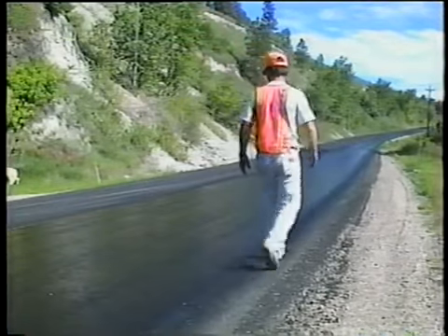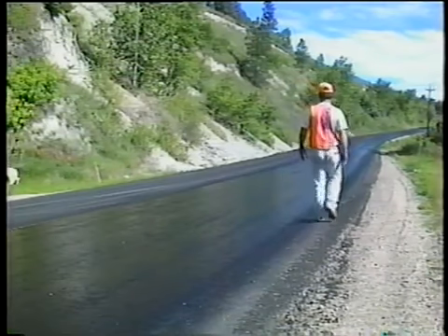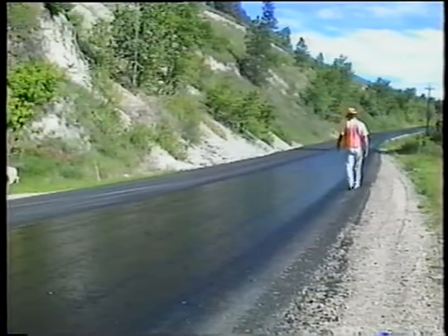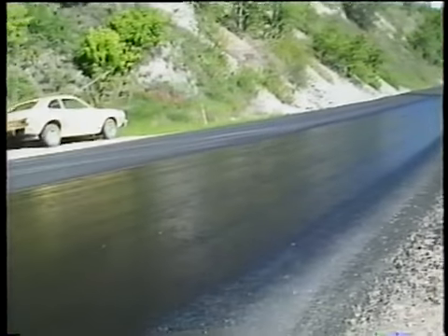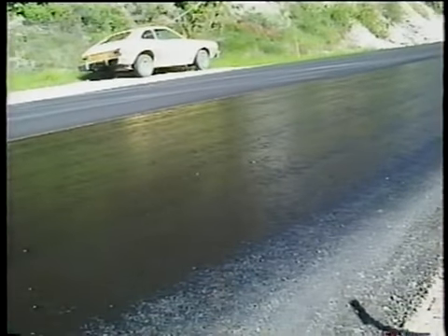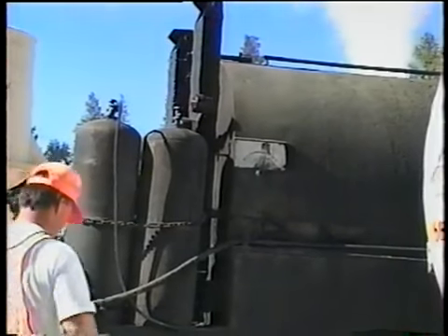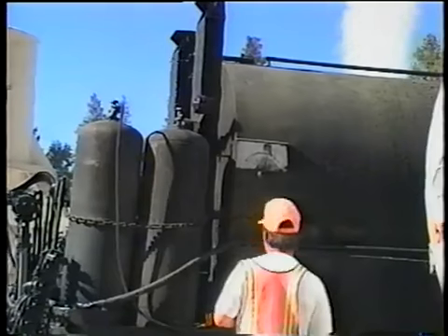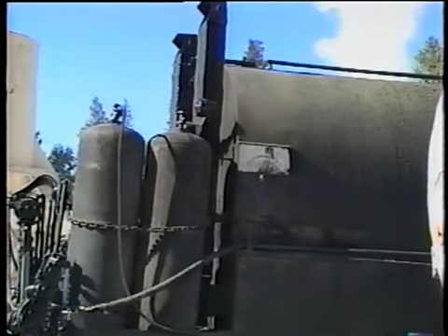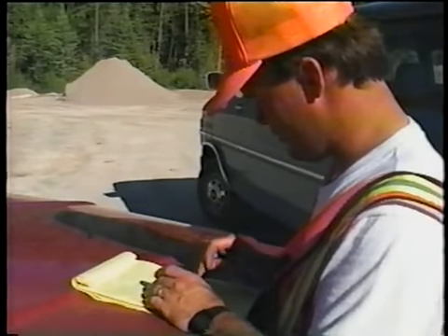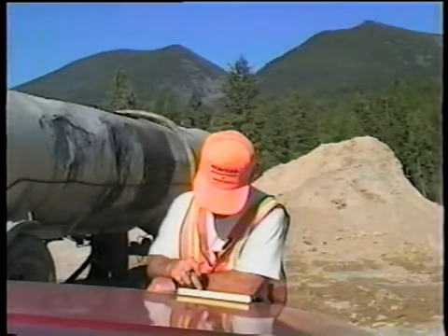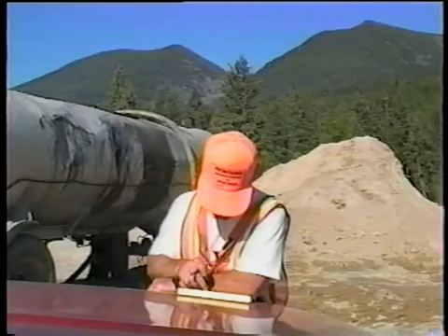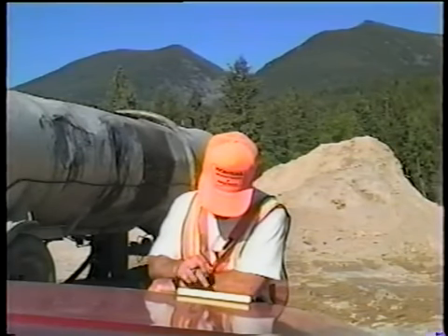Look over the application closely. If you see any bare spots or lightly covered areas, stop the distributor and get the problem corrected. It could be just one plugged or misaligned nozzle, so make the necessary adjustments. After the material has been applied, be sure to record the number of liters remaining so you can calculate the application rate. To do this, you divide the number of liters of tack applied by the area covered: the length of application times the width in meters. The rate is so many liters per square meter.